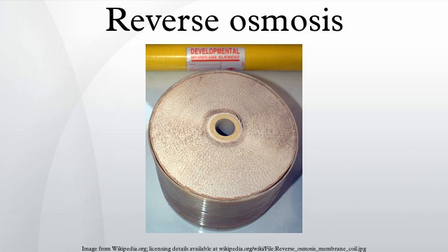They are capable of 3 kWh per cubic meter or less energy consumption. Examples are the DWEER, the rotary pressure exchanger, and the Danfoss iSave. Energy recovery pump, a reciprocating piston pump having the pressurized concentrate flow applied to one side of each piston to help drive the membrane feed flow from the opposite side.